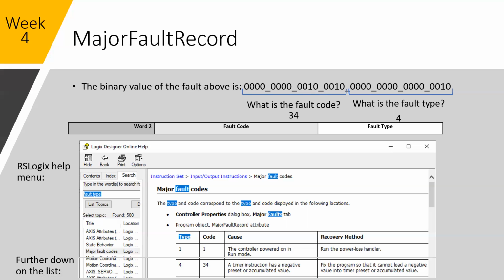And this might sound pretty straightforward, but sometimes operators, if you need to change a time delay or a length of time for something, the display value, they might hit 0.1, but the point is actually a negative, and they might write in -1 and fault the controller if it's not programmed to protect itself.